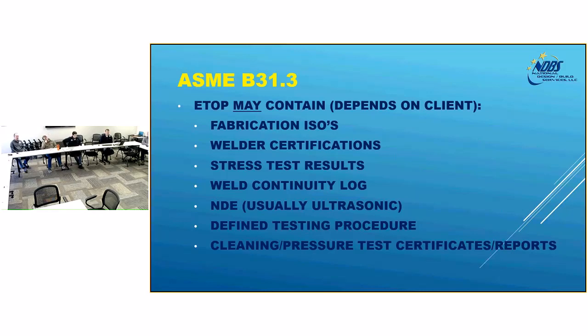Now, some people may look at that and say, well, for us, a signed-off hydrostatic test form is a must. We're not even going to let an owner tell us they don't need that, because if that pipe springs a leak under the warranty period and somebody gets hurt or we have to shut down production, we're on the hook for that.